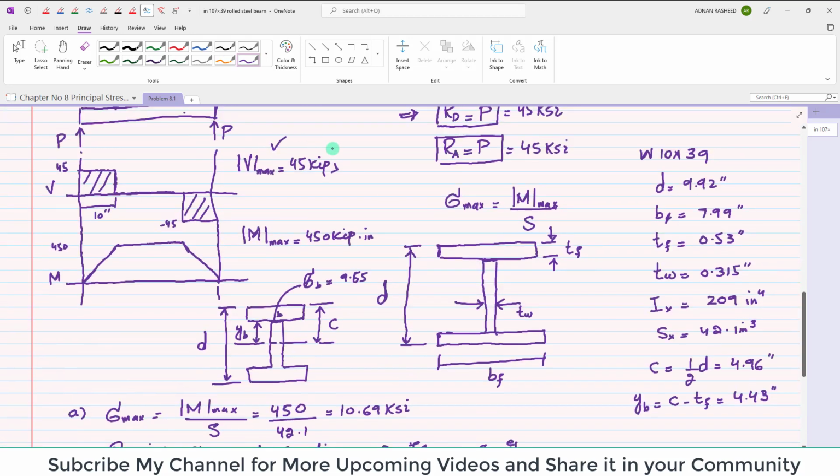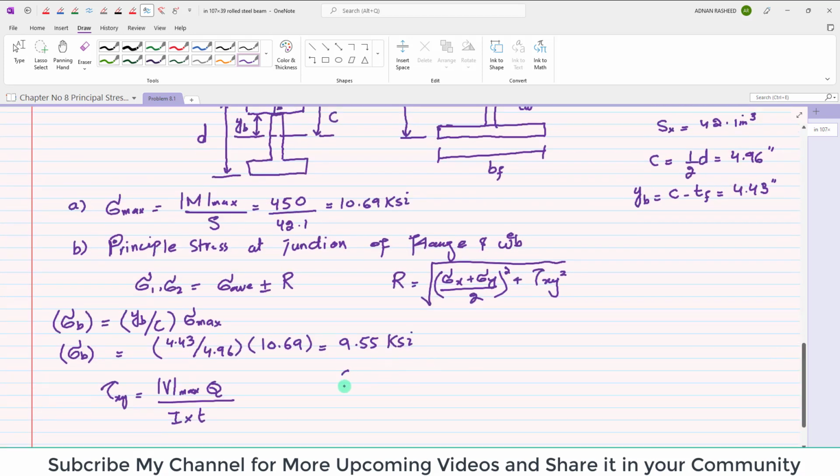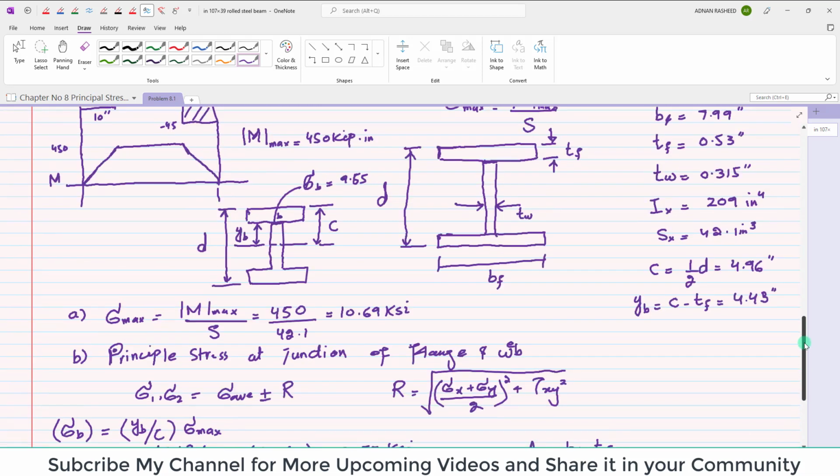We do not have Q, and Q is the first moment of inertia, that is equal to area into YF dash. Now area of what? We will take the area of flange, because at the junction of web and flange we have this area. Clear? So area of flange is equal to breadth of flange into thickness of flange. So you have breadth and thickness as well.